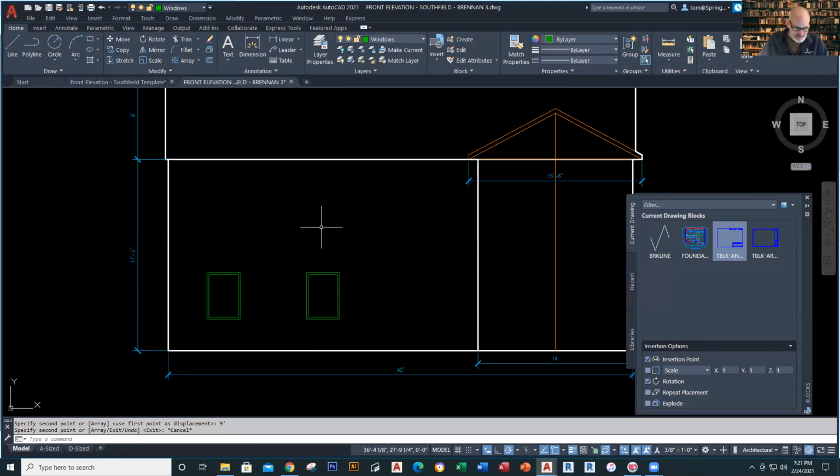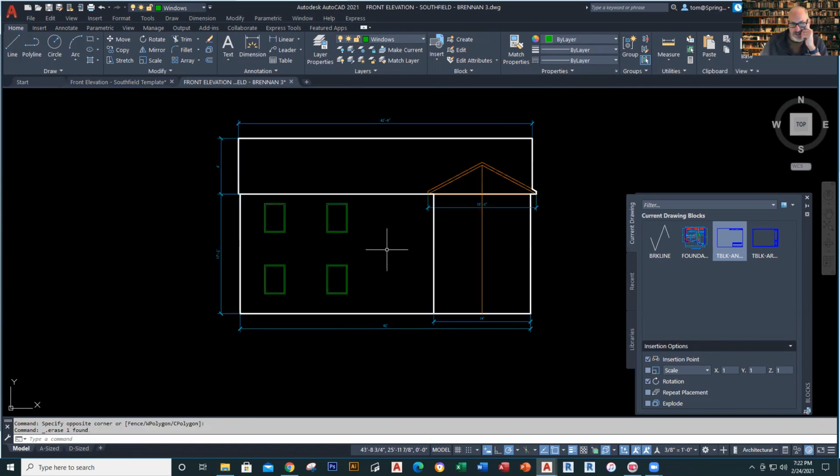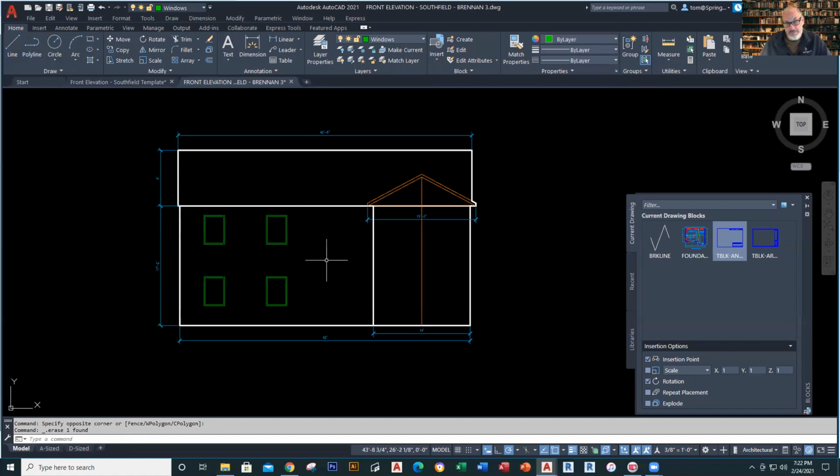So those are there. And then I have these that are above, and they need to be 11 foot 8 from the bottom. So I'll go here and click there, and 11 foot 8. Just to mark it, once again, I'm going to copy. I'm showing you right here some quick methods to get these to show up where they're supposed to. Go to here and then to here. Boom, there they are. And that's how we place those. Okay, now as we have these in place, we're looking pretty good.